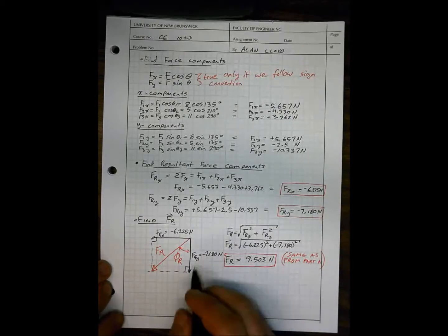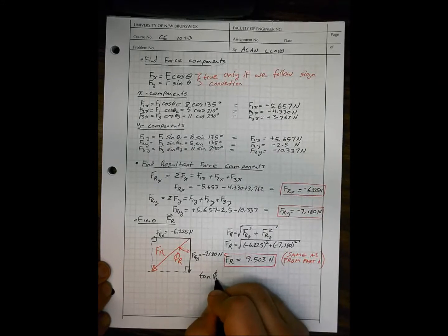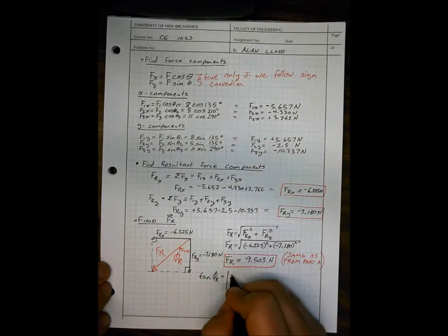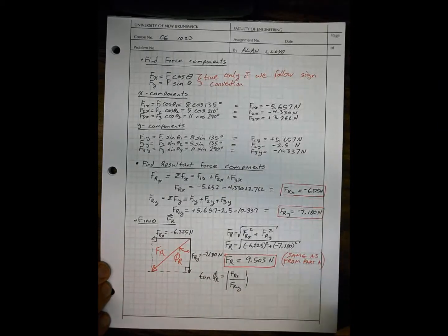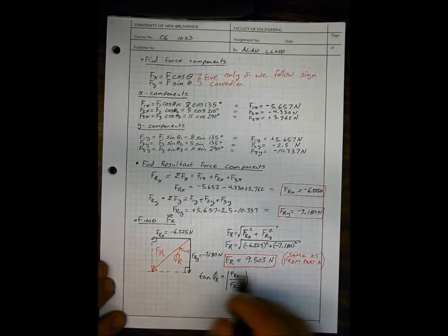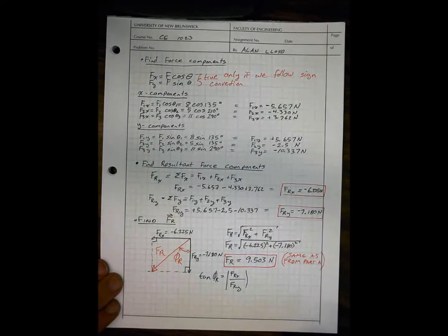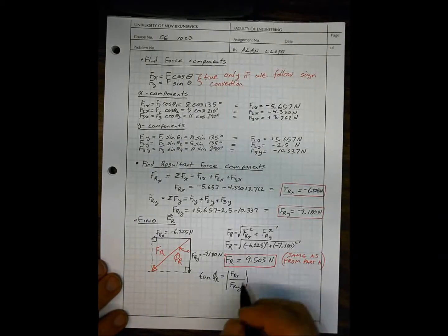Now, that's not hard to find. We know that tangent of phi r is equal to the absolute value of Frx over Fry. We put that absolute value in there to ensure that this plus or minus sign doesn't come back to haunt us in terms of determining this angle. Because we're doing this angle quite visually, we don't need to worry about negative or positive signs of the force component values. And we'll put in the appropriate rotation off the appropriate axis manually later without including a sign.